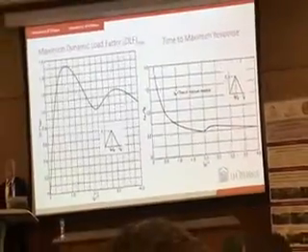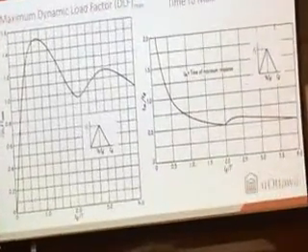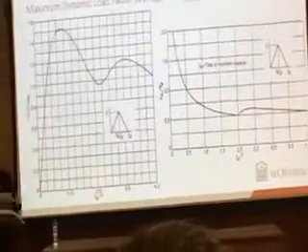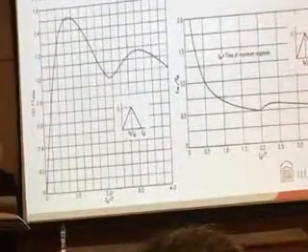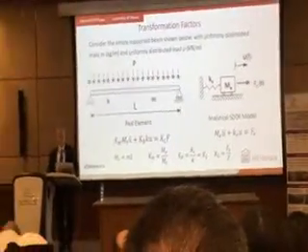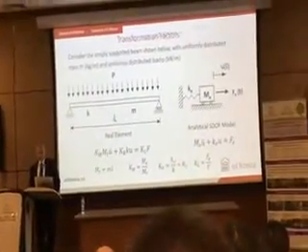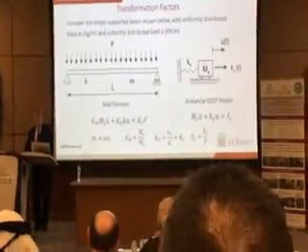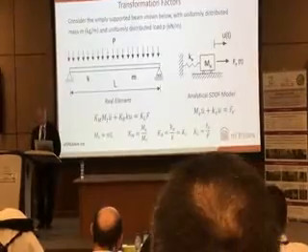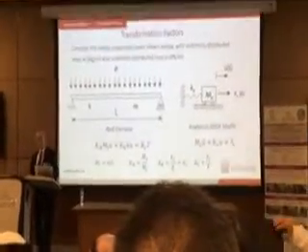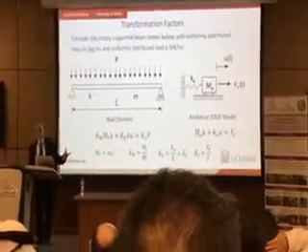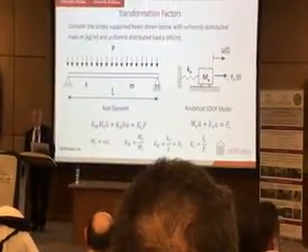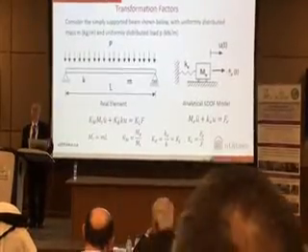There's another maximum dynamic load factor chart. This time it's a triangular load that is similar to sidewall loading. So these design aids are available. But then all of these deal with a single mass spring model, right? And you have to have concentrated lump mass for those equations and those charts to work. And you have to have concentrated load as dynamic force for them to work.